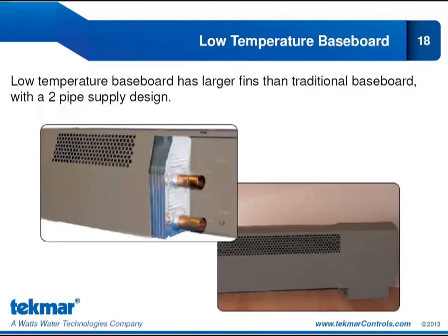We also have low temperature baseboard now. This type of baseboard has larger fins than traditional baseboard with a two-pipe supply design. The fin area is about 3 times larger than typical baseboard. And at a supply temperature of 110 degrees Fahrenheit, the heat output is just under 300 BTU per hour at a flow rate of a gallon per minute. So very different from conventional baseboard that's typically designed for supply temperatures ranging from 160 to 200 degrees Fahrenheit.